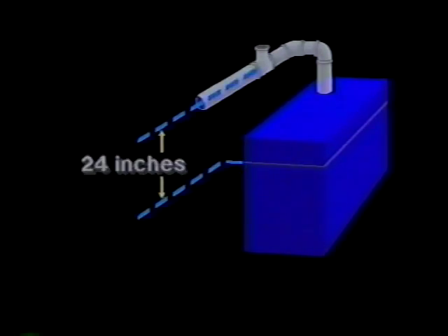You must also allow a minimum of 24 inches between the boiler water line and the header center line. Anything less than 24 inches increases the chances of water hammer and insufficient or wet steam.